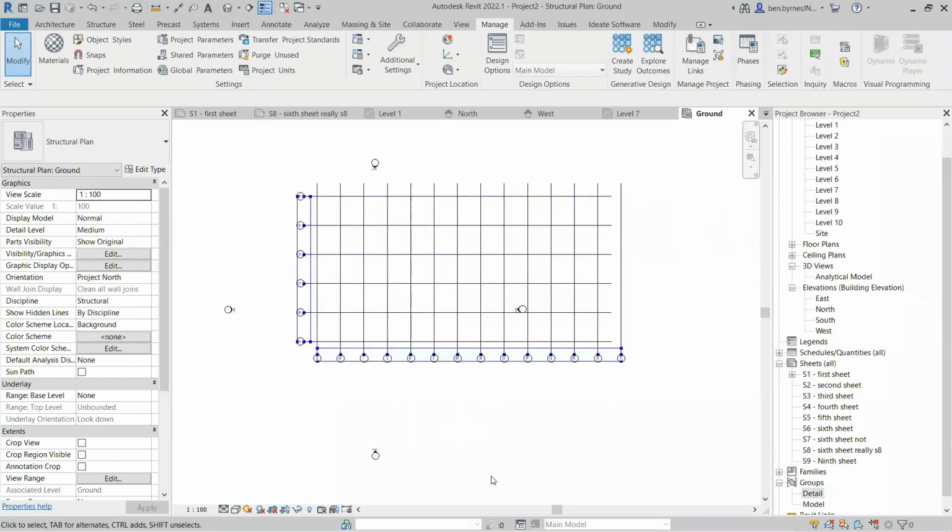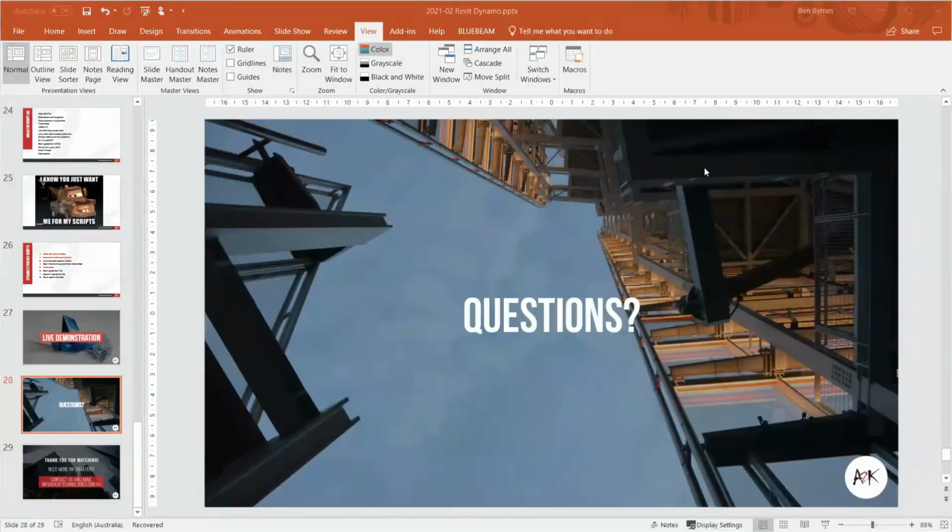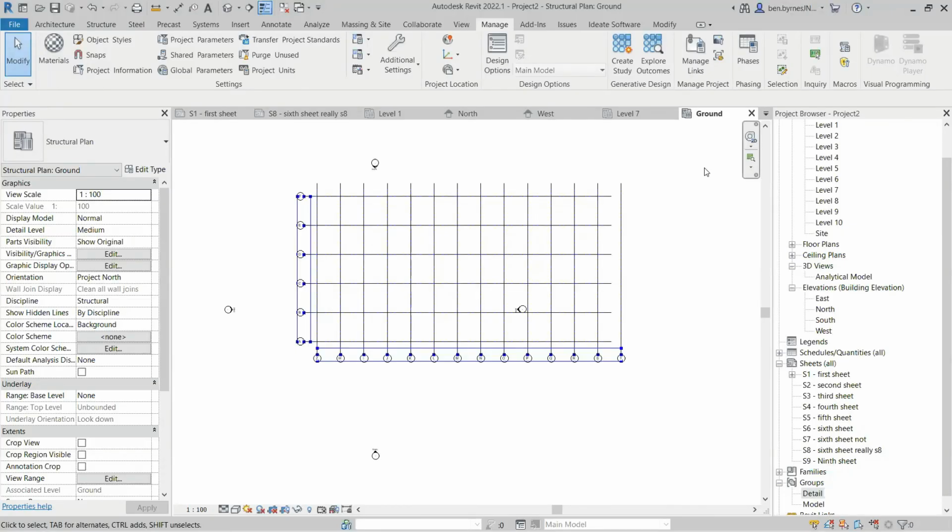So it's really like almost like a macro that's running in Revit. It's a bit funny, even though they're technically inactive, it is opening the file, making the changes and then closing it. So that's really how the update one works as well. It does actually open the file, update it, and then close it down.